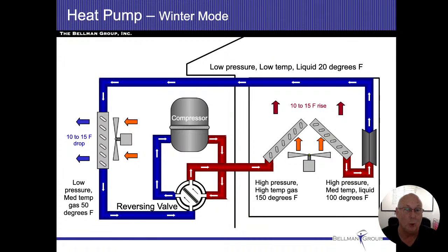But when we use those terms, the difference between a heat pump and an air conditioning system is that reversing valve. In this diagram, you see it on the bottom there, and that changes the direction. So right now, this is in winter mode. So right now, we're absorbing heat from the outside, and we're bringing the heat to the inside of the house. I do want you to take note of the temperature rises, all right?